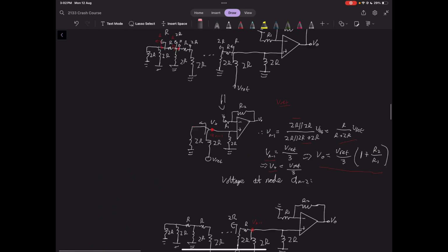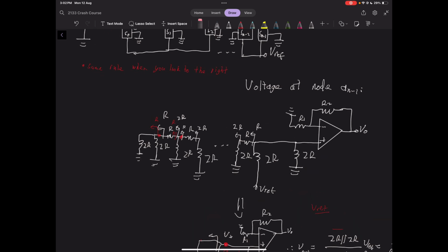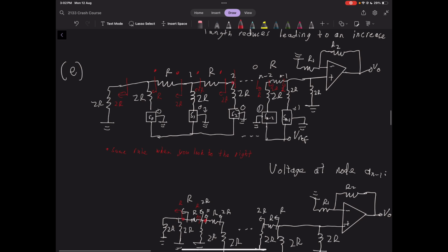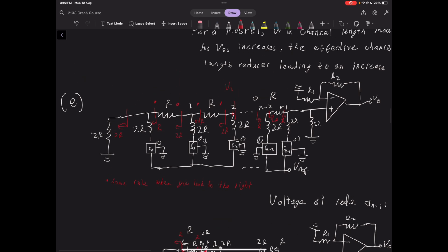And hopefully that should make sense, because if we look at the whole circuit, if this node here is, we'll take this node here as an example, V2, and let's say that there's no more nodes, so then this node would be V3 and that node would be V4. V2 would have to drop half its value over here and then half its value over here, and that would be 1/2 squared. V1 would drop half and then half and then half, and it would be 1/2 cubed. And it's because the entire circuit is symmetrical, and every time you voltage divide from one node to the other, it drops by 1/2, and this equivalent resistance pattern holds.